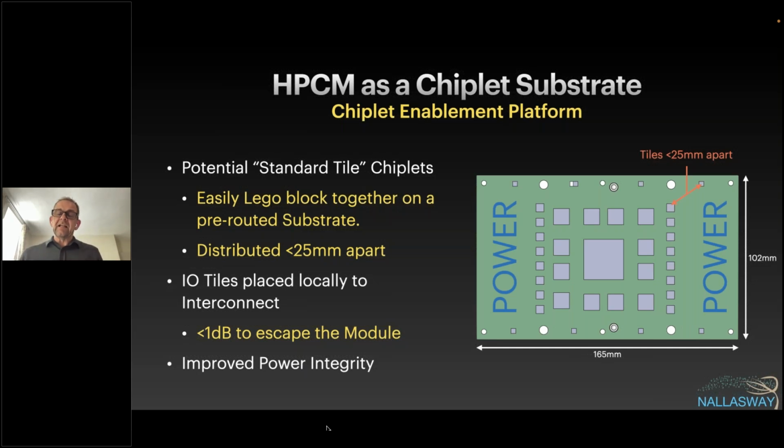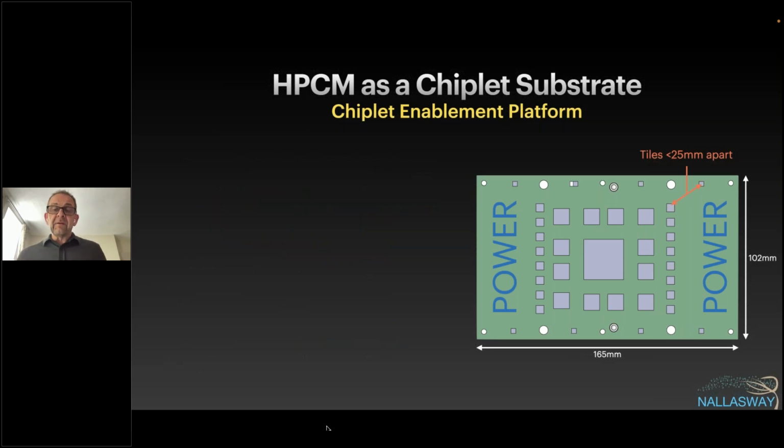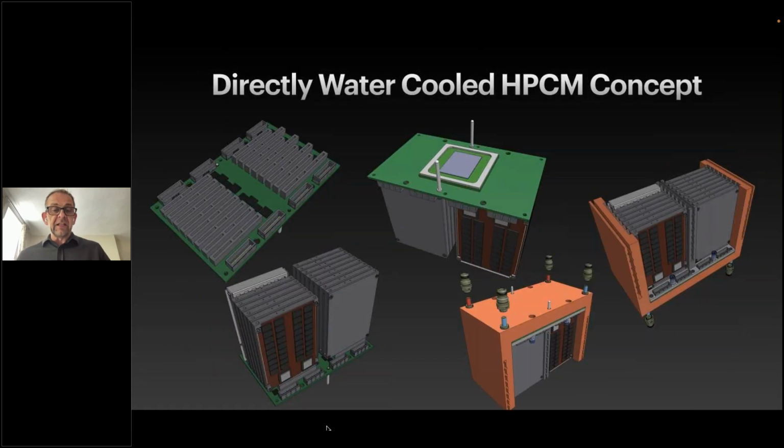Right. Exactly. So if you look at NVIDIA, their NVLink, I think they've got 4 or 5 different PHYs for these different reaches, from chiplet to package to package. Exactly. And by the way, that's really the whole idea of these modules. If you look at the proximity of these media modules with their controllers to the big chip, you're in the region of 5 to 10 dB apart. IBM kindly did a simulation for us, and we were sub 10 dB for PCI Gen 5. I think it was about 7 dB if we unpackaged the processor chip and put it down on the substrate on the OEM.